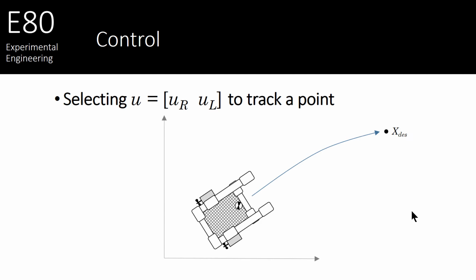Well, we're going to have to figure out how to spin these little propellers, because when we spin these propellers, they're going to generate a force, one from the right motor and one from the left motor. Now these forces are functions of the output of our controller. We're going to call these UR and UL. These are signals that our controller is going to spit out. And we're going to note that the size of the force output from this motor is obviously going to be a function of the control signal that we send to it.